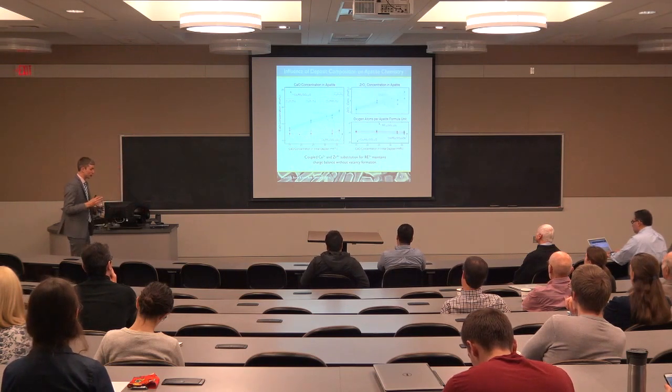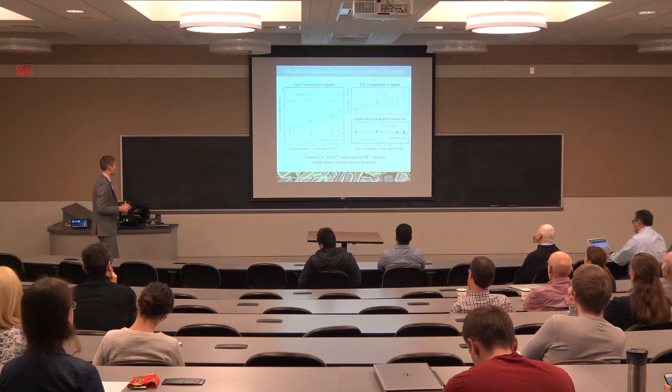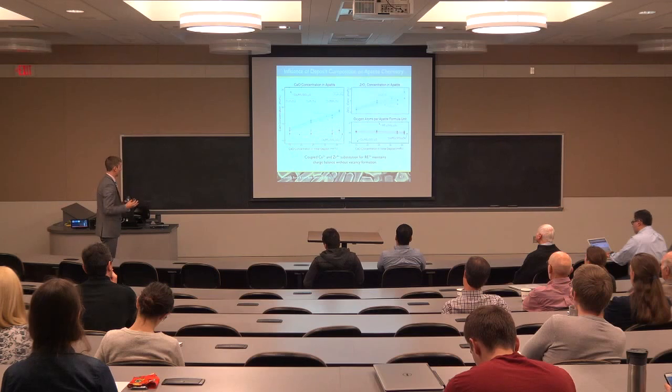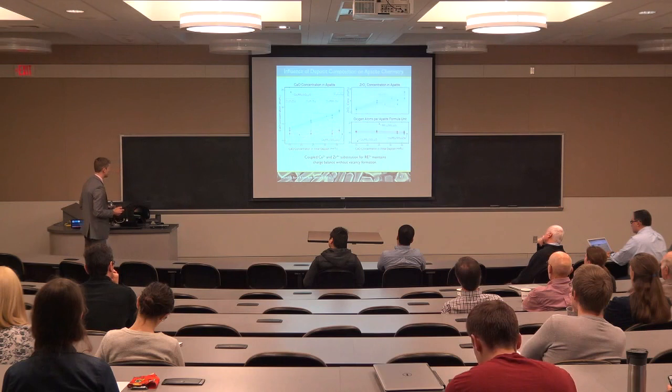And this tells us that there must be a really large energy penalty for these apatite compositions that involve vacancies to form. And so this also says that if our goal is to produce as much apatite as possible, we really need some of the zirconia there because that's going to facilitate this wider range of compositions that better consume the molten deposit.